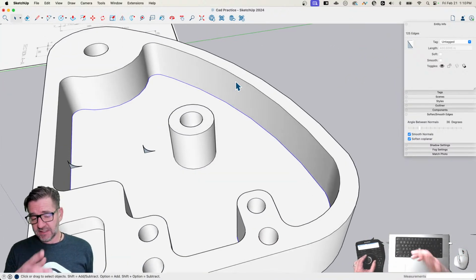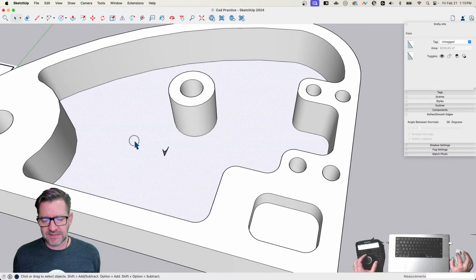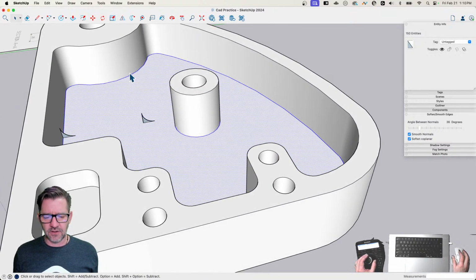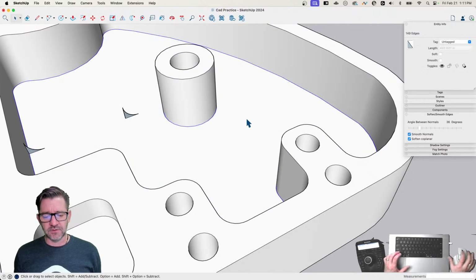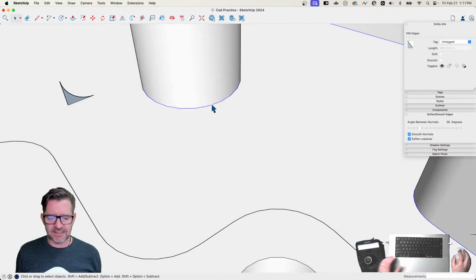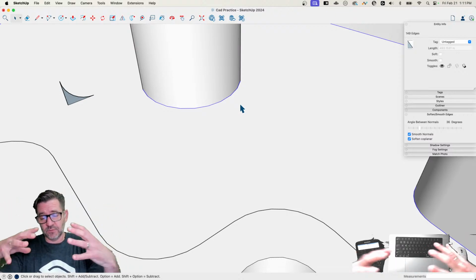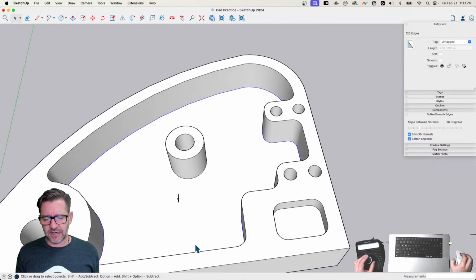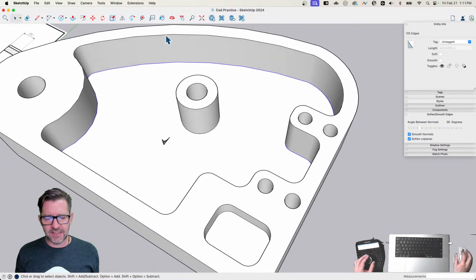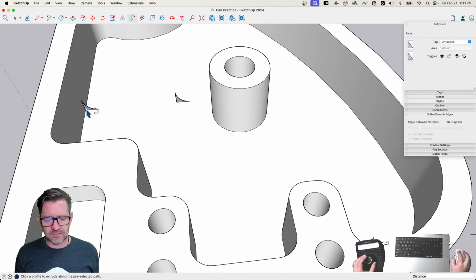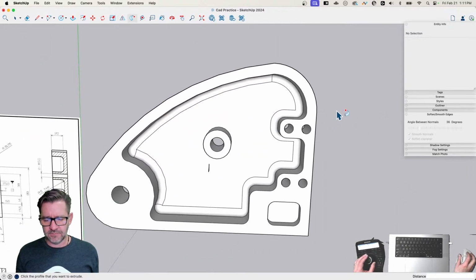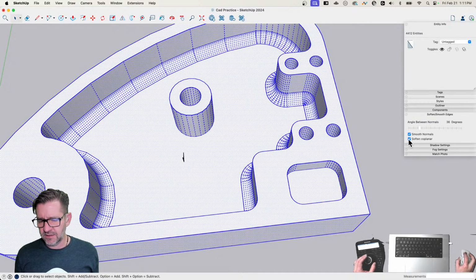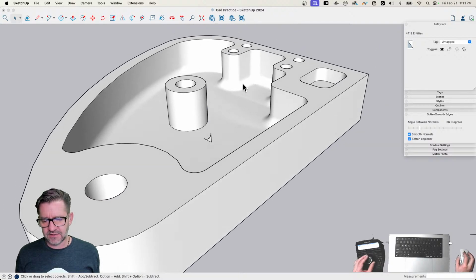So in a complex shape like this, it can sometimes be tricky to get the edge. But if you pick a face and double click the face, it'll highlight all the boundaries of that face. So that gets all the edge that I want. And then I can shift click to remove the face. And in this case, I got this other edge too, because that whole face was defined also by this. So I can just turn that off, and that leaves just the boundary I want to follow me. So with that highlighted, I can just click follow me, and I can hit a little face, and there we go. Edges are softened and smoothed. Again, I can triple click, toggle soft and smooth, and then I get that nice rounded corner.